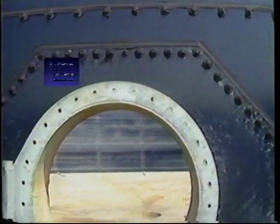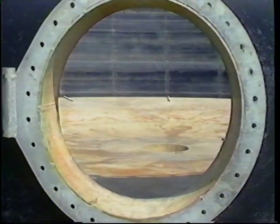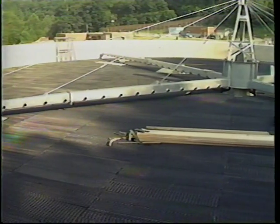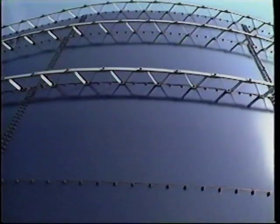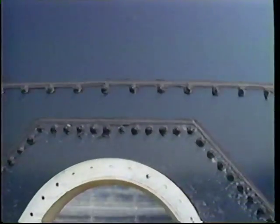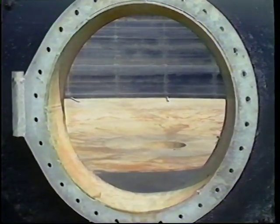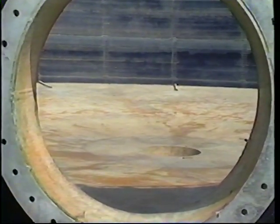First, let's take a look at the retaining structure. The structure houses all of the other major components of the trickling filter. The structure may be either round or square and could be anywhere from 4 feet to 50 feet tall, depending upon the design of the filter. Materials commonly used for the construction of trickling filter structures include concrete and a special ceramic coated steel.